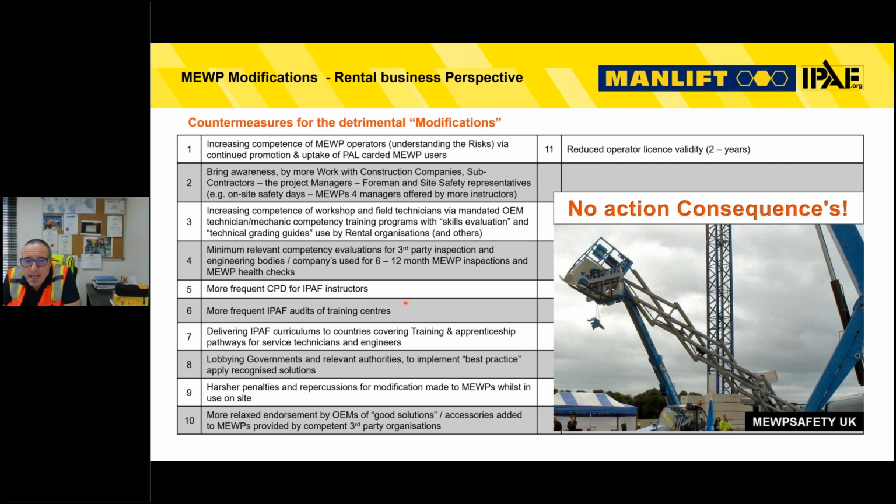I'll read these out. We need to increase the competence of MEWP operators. So we need to understand the risks, and operators need to understand the risks of modifications. So we need to continually promote and uptake. I recommend very strongly the Powered Access License system by IPAF. So Powered Access License holders, MEWP operators, should have a PAL card.